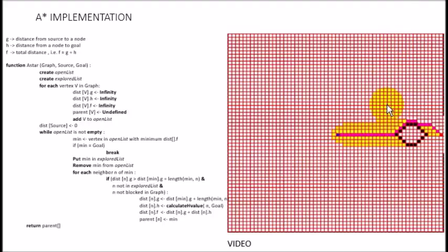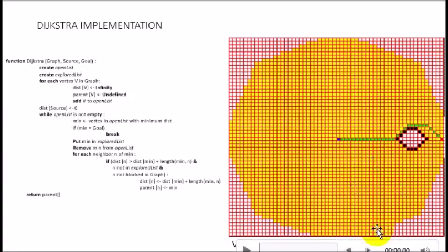The final path consists of explored cells of only this much yellowed region, while in the case of Dijkstra's we have filled all over the region while calculating the minimum path. While the minimum path happened to be the same in Dijkstra's and A star, in Dijkstra's we covered all the region while getting to the minimum path.